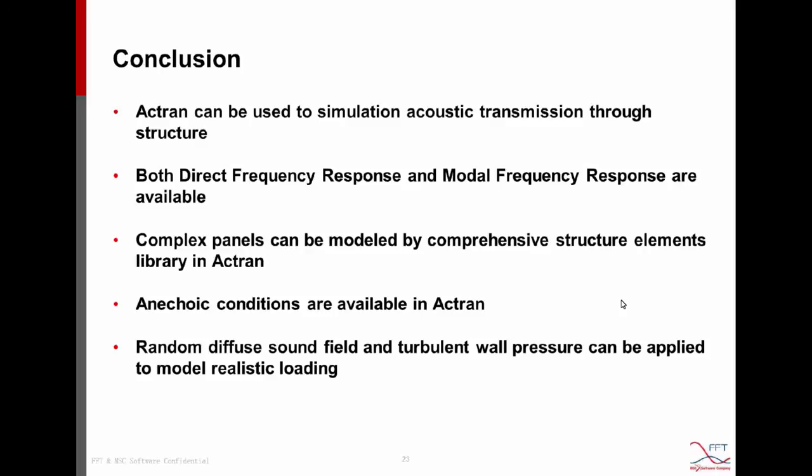So if we use direct frequency response, we can model the complete structure in Actran using its comprehensive structure element library. Anechoic conditions or any cavity conditions on the reception side are also available in Actran. And random diffuse sound field or turbulent wall pressure can be applied in Actran to model realistic loading conditions.